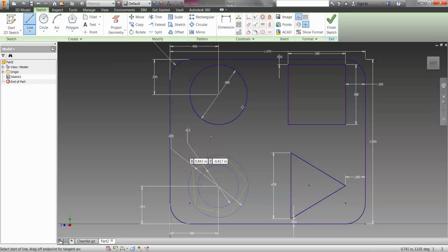Now before we draw our line, we want to come over to our construction and turn that off so that we have solid lines now as we're working here. So I'm going to find the center, these points here of our pentagon, and start our line at the corners there and come down to our circle, and then we're going to go back out to the pentagon. And so we're going to just continue to make our lines like that around the pentagon the whole way, creating this star shape. It'll be nice and even once we have created our other constraints.